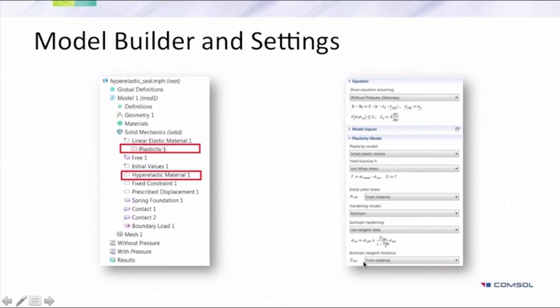But you can also change this and type the equation or the number directly. Wherever you can type a number in COMSOL, you can type an equation, so that this, for example, isotropic tangent modulus can depend on other parameters. I think probably a better example is the yield stress, which frequently depends on the plastic strain. So here you can actually type the yield stress as a function of the plastic strain or another variable.